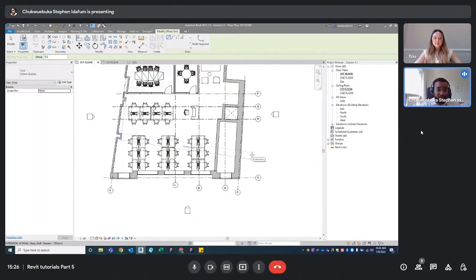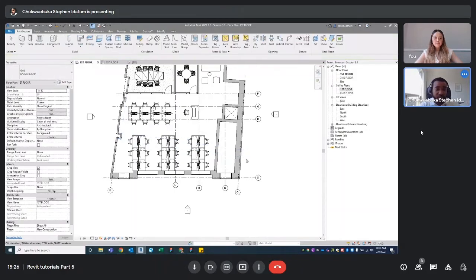But grids are really important in working drawings to show the constructability of the walls and their extent, so that contractors know where they're placing each wall and how the walls are connected, whether they're connected to the underside of the ceiling or the underside of the structure, if it's an existing or a new building.